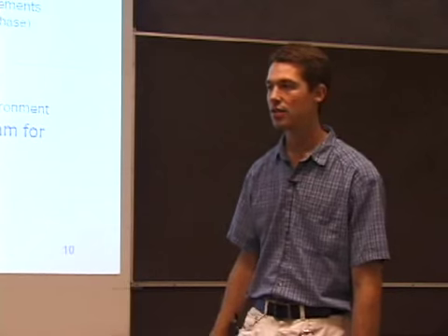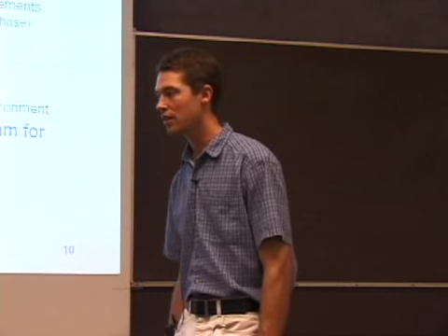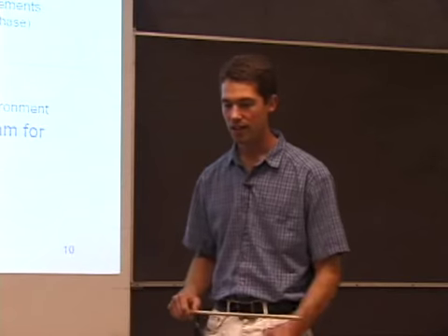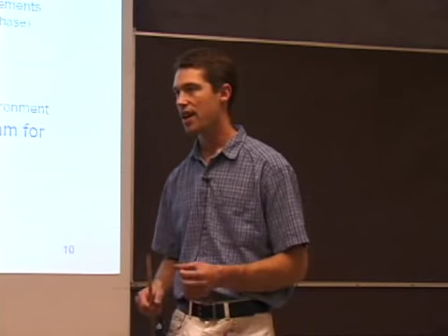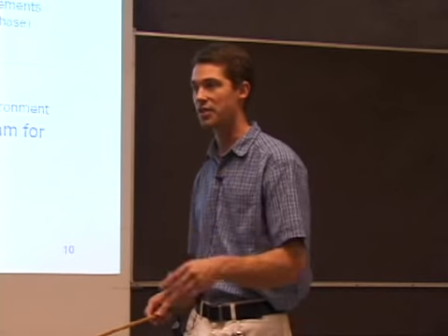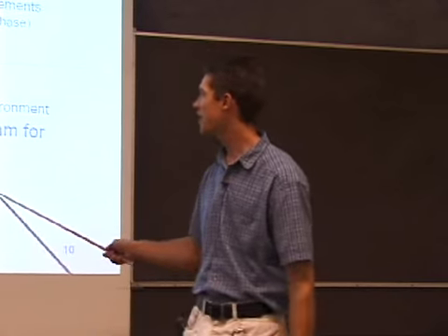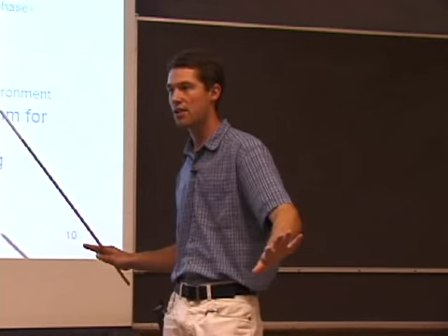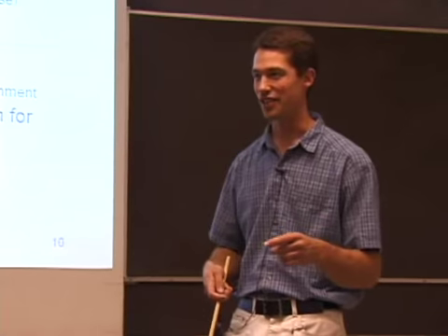So what do you mean by detailed noise tracking? This is where we get to put in things like the DAC noise and represent it as zero crossing blips. We do our best to represent essentially right down to the level of bit flipping noise that happens in a DAC. And what's the DAC? The DAC is the digital to analog converter.